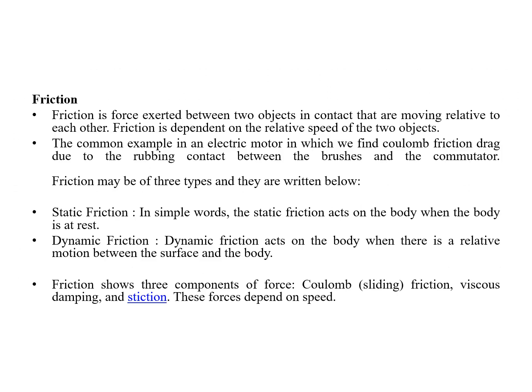Coming to the next nonlinear element, friction. I hope you have studied friction in your physics. Friction is the force exerted between two objects in contact that are moving relative to one another. So friction depends on the relative speed of the two objects. A common example is the electric motor, where we find Coulomb friction drag due to the rubbing force between the brushes and the commutator.